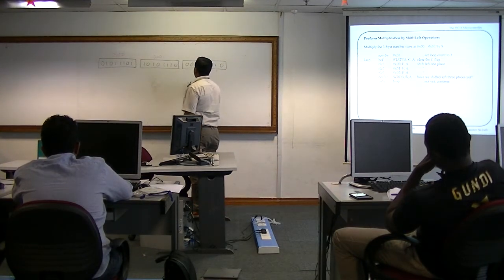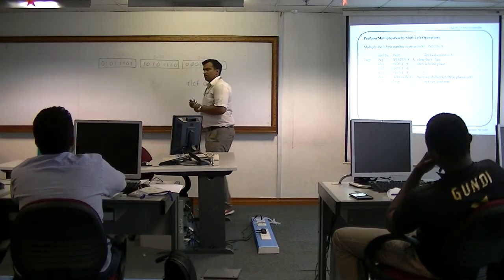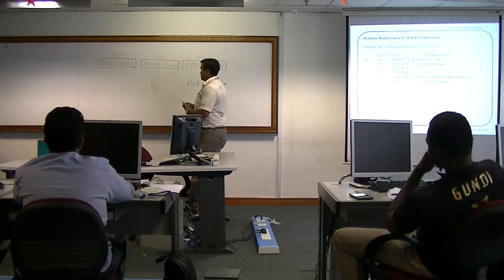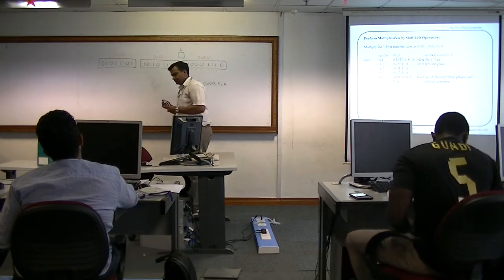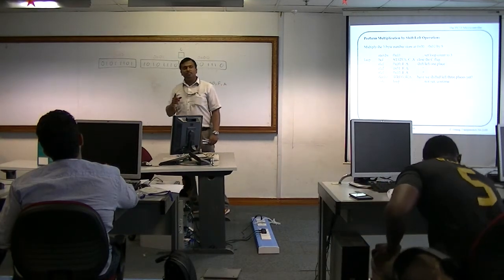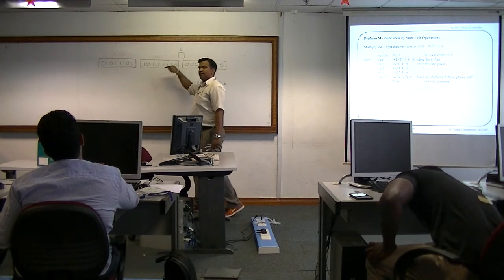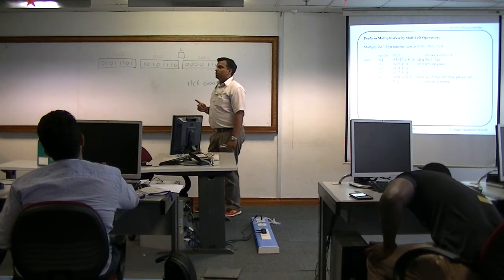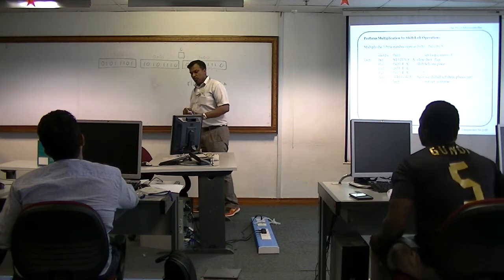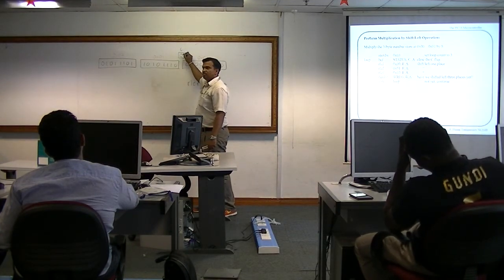So you use rotate left through carry, extended. So what happens? You have a carry bit here. Now remember the rule: because you rotate left, whatever enters the least significant bit must be 0. So in order for that condition to be true, you must always make sure that the carry bit's initial value is 0.